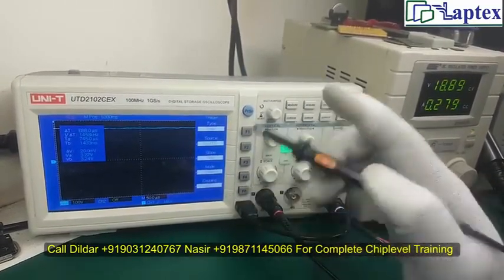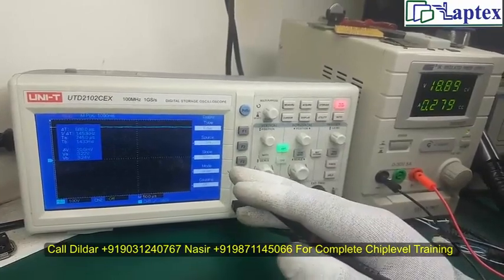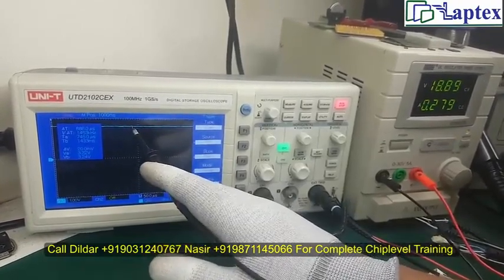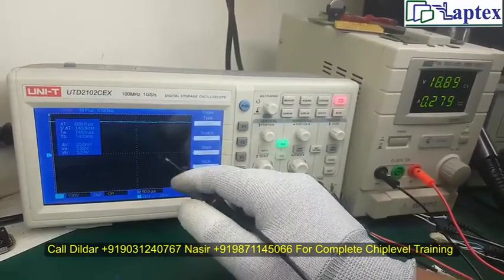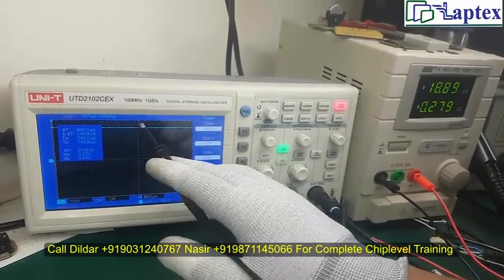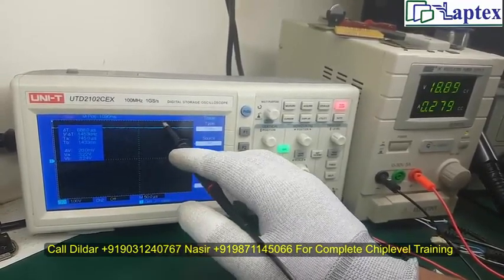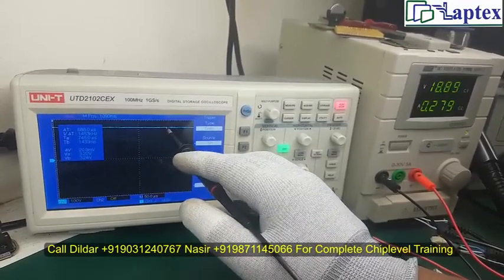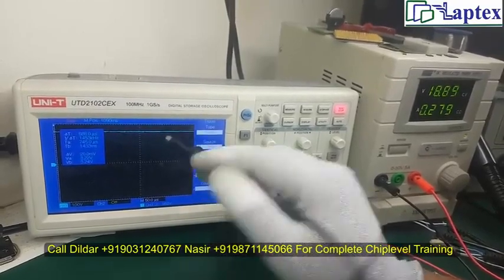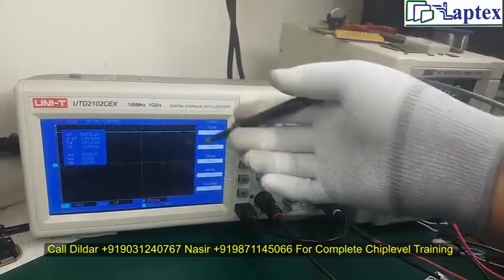Okay, so on these two points of the BIOS, you just don't need to get any clock signal or any data on the DSO. One is the write protection pin and the other is the hold pin, and the hold pin could be named the reset pin. Okay, so now let's move forward.